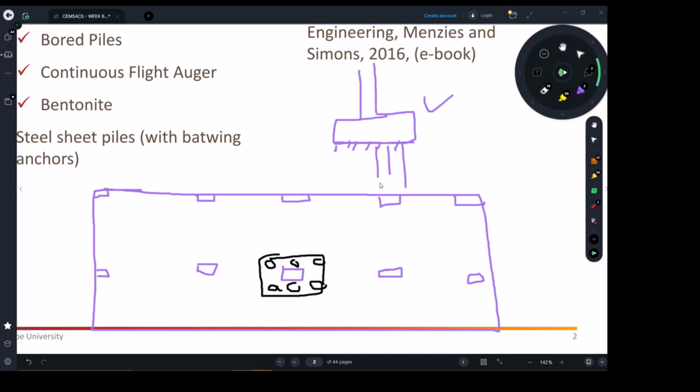So that's what I was talking to you about. Then my piles will be here. You've got 3 this side and 3 the other side. So basically that's what I was showing. And same thing for this. Maybe if we have a small column which takes less load, the pile cap looks like that, and we may end up having only 4. Sometimes we have 3. And the engineering drawings will tell you each pile will take 1,000 kilonewtons or 1,500.